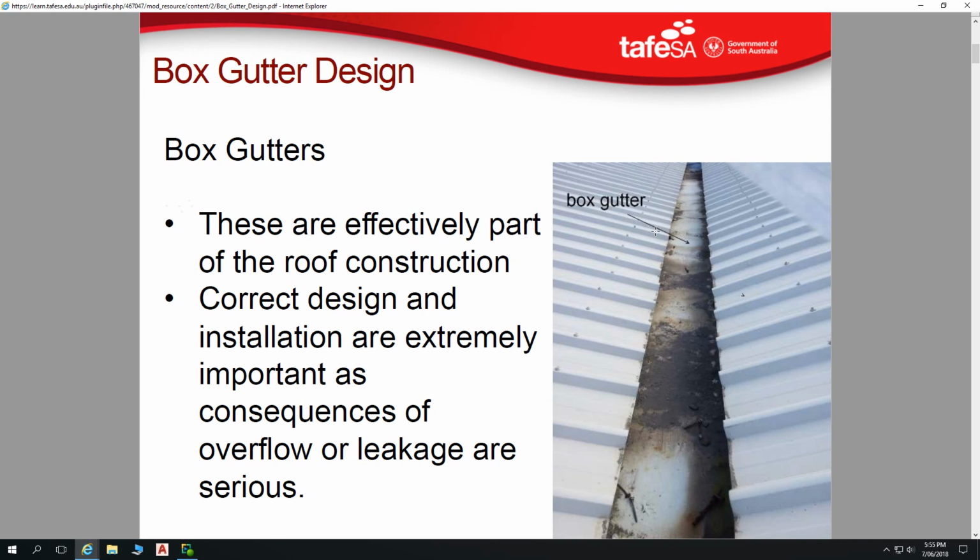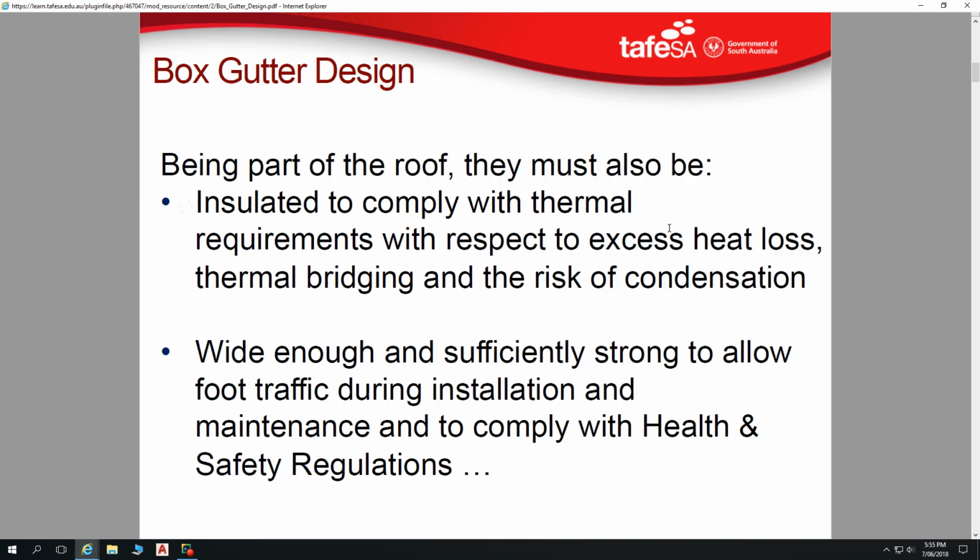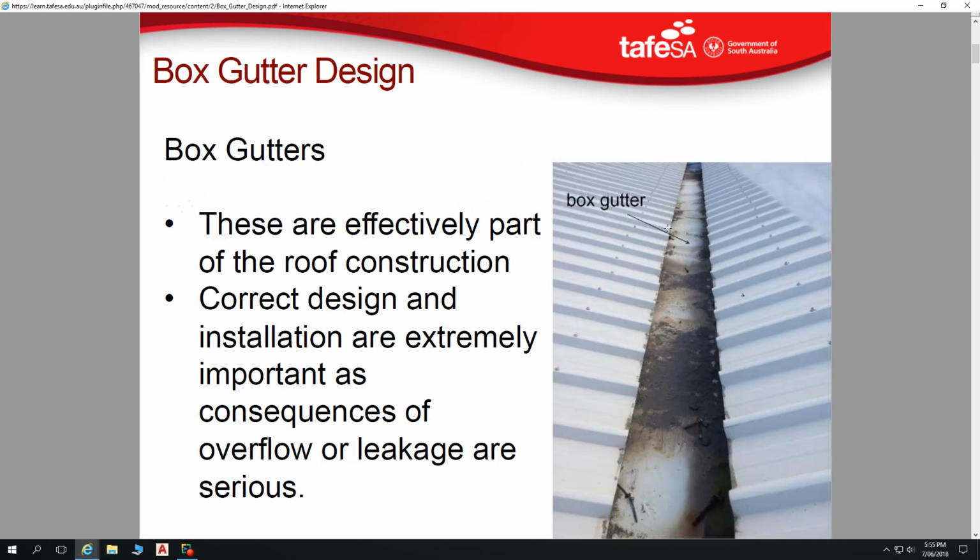And so it's understandable that people under-design box gutters and that they install box gutters without significant fall. But then there's also people who specify box gutters without giving much consideration to the fact that there has to be significant fall on those box gutters, and not sizing them correctly. Previously it's been a fairly laborious task because they've had to be designed in accordance with the Australian standard. But in recent years, some smart cookie, I don't know who it is, but it's very handy.